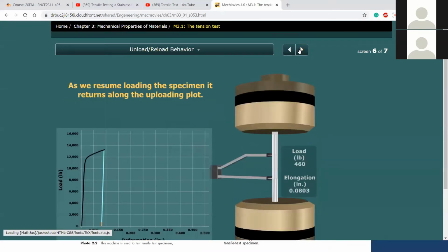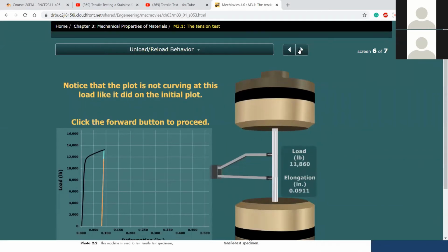Is the elastic region the range that is linear? Yes. And the plastic region is whenever it starts to curve? Mm-hmm. Okay, the elastic region is the linear portion, and when the change starts from the linear region to a curve, that's where your yielding point is. At this point, you are leaving the elastic region and getting into the plastic region. Okay, I got it. Thank you.